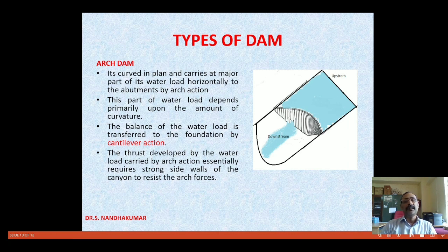Coming to the types of dam, the arch dam is another type. The wall should be curved in nature, as you can see in the picture. The thrust of the impounding water and the weight of the dam, the balance of the water load, is transferred to the foundation by cantilever action. Cantilever action is nothing but